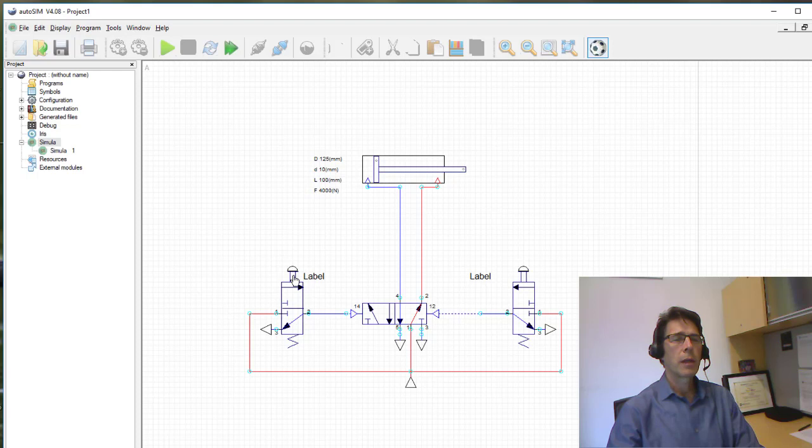So if I press the first push button, you notice the valve extends. If I press the second push button, it retracts. So what's happening is pressing the first push button moves the pneumatic so that it allows compressed air to flow into the first pilot control, pushes the valve this way. There's no spring return or anything, so it stays in that position. Then I push the second push button and it moves back. So that's just basic 2-button pneumatic control. And notice I don't have to hold the button down because once the valve moves over, it stays there. Kind of a built-in latching effect.